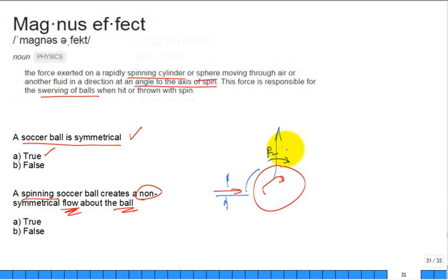There's another way of looking at it. If I have the ball and it's spinning, here the spin surface and the flow are in the same direction, hence they have less reason to separate. And so the separation point is delayed, where here the spin surface and the flow are more adverse, so to speak, and it's earlier separation, not later separation. You're changing the separation points on the backside. One, you're delaying separation and the other, you're advancing the separation.